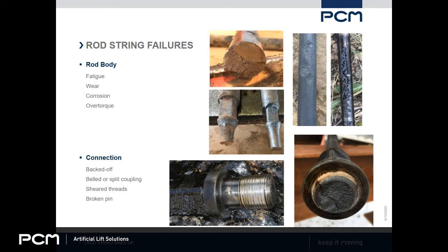Wear. In most applications, rod wear is not a big problem, but I know there are some people listening today who have some pretty significant rod wear problems, just because of the nature of their operation. Most of the time, you get a hole in the tubing first. So you have to pull the tubing, and when you're pulling your tubing to replace it, you should always be inspecting your rods and making sure you're not running anything back in that's badly worn or corroded. So it reduces those problems.